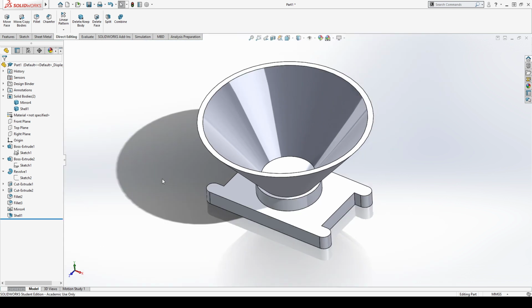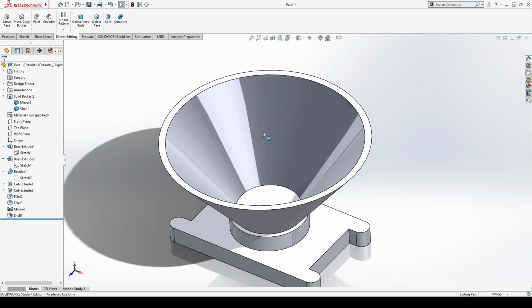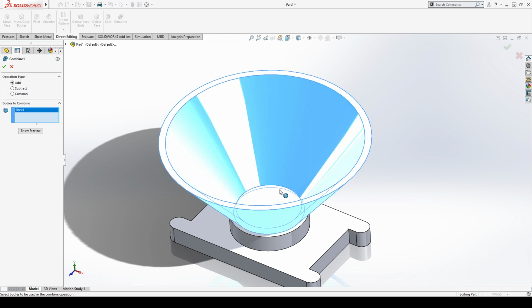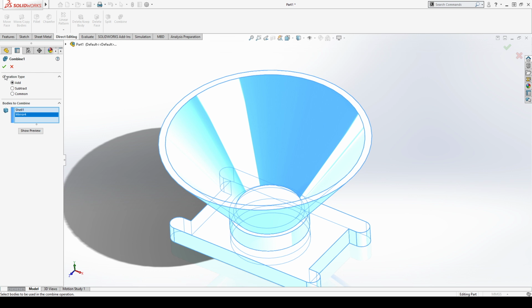So that's a really nice way of smoothing up your process. If you just want this cup specifically to sit on top of whatever this is, and get shelled out all the way to there, you can go back to your revolve, make sure you don't merge it, work with it as a separate solid body, and then once I want to combine it back into one part, just click on both of those. Up here I have my different types of combines.